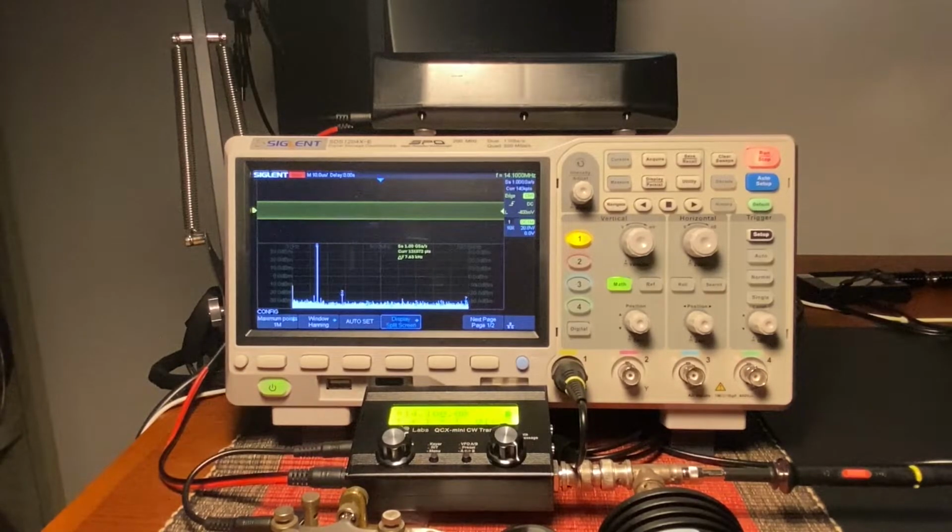It's true that many scopes have FFT tools that are limited, but the Siglent 1204XE seems to work well for the purpose if it's set up properly and its limitations are understood. Mine gives useful results for harmonics below 200 megahertz. Above that frequency, the bandwidth of the analog circuitry will cause incorrect readings. It also makes no attempt to hide any internally generated low-level spurious signals, and one must be aware of any that might be mistaken for signals from your device under test.